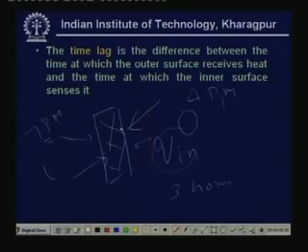This is the reason why, if the outside temperature is maximum at say 3 p.m., we find that the indoor temperature in an unconditioned room is maximum at say 7 p.m. or 8 p.m. For example, at midday, at 12 o'clock, outside may be the hottest, but the room temperature will be very high not at 12 o'clock, but maybe at 3 or 4 o'clock.